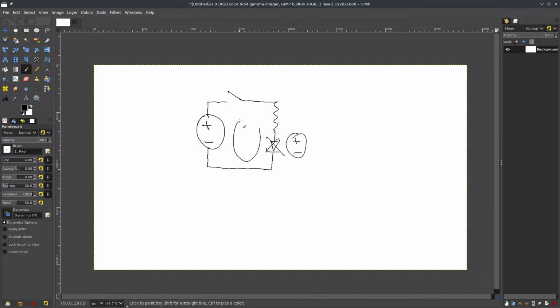Then we calculate a loop here. If this is VN, and this is VD for V diode, then at that point it'll just be Ohm's law, so it'll be VN minus VD divided by R equals our current. We want 10 milliamps usually, so we do 10 mA and solve this equation. We multiply by the resistor, divide by 10 milliamps, and that'll tell us what value we actually need.